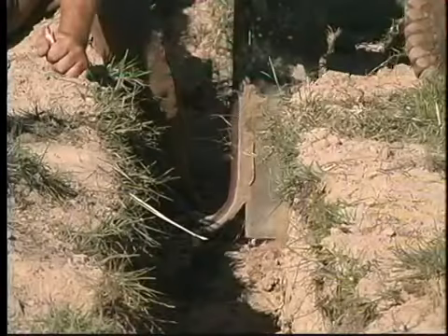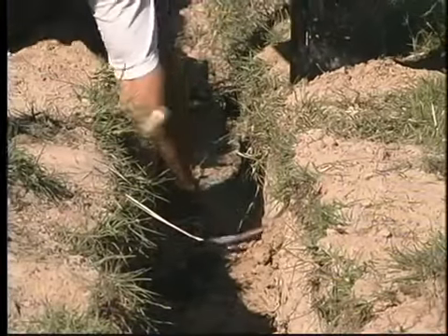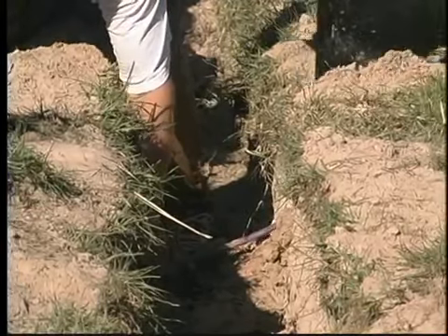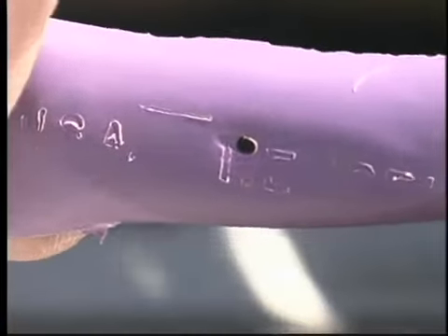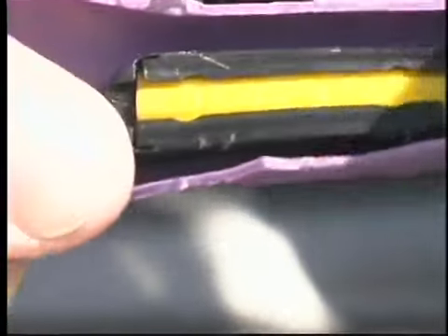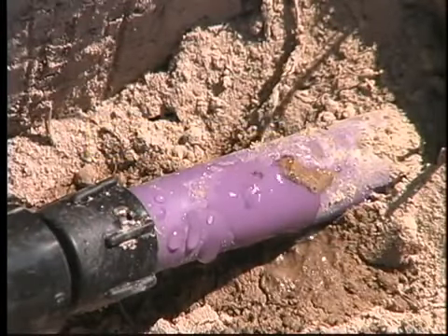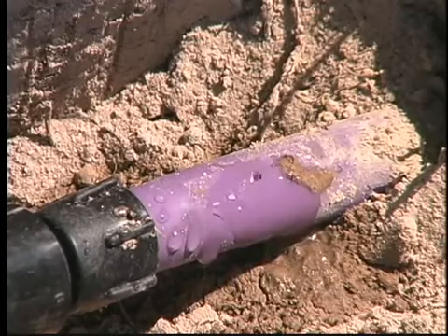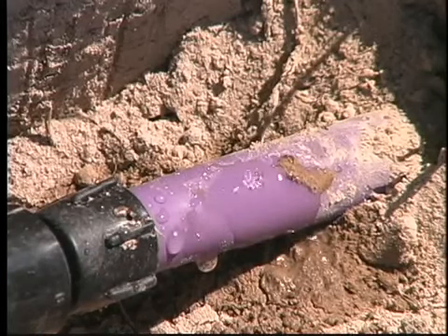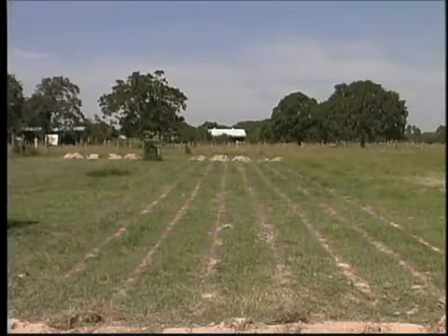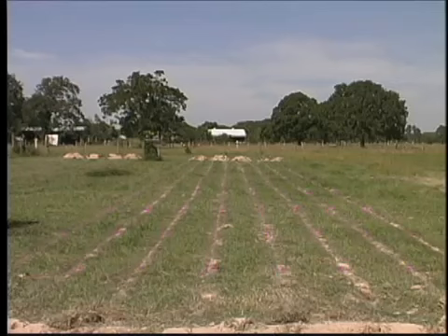The drip tubing is placed directly into the soil without the use of media-filled trenches. The system relies on drip tubing with emitters to reduce the water pressure before it enters the soil. Since the emitters in the line have the same emission rate, wastewater is uniformly applied to the dispersal field. The drip field is constructed to spread water across the landscape.